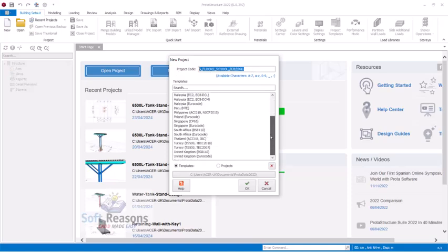After which you have to select the code template. So we're using United Kingdom BS 8110. Select that one, and then after which you can click on the OK. But if you want to extract code from your existing project here, we use this project options, right?